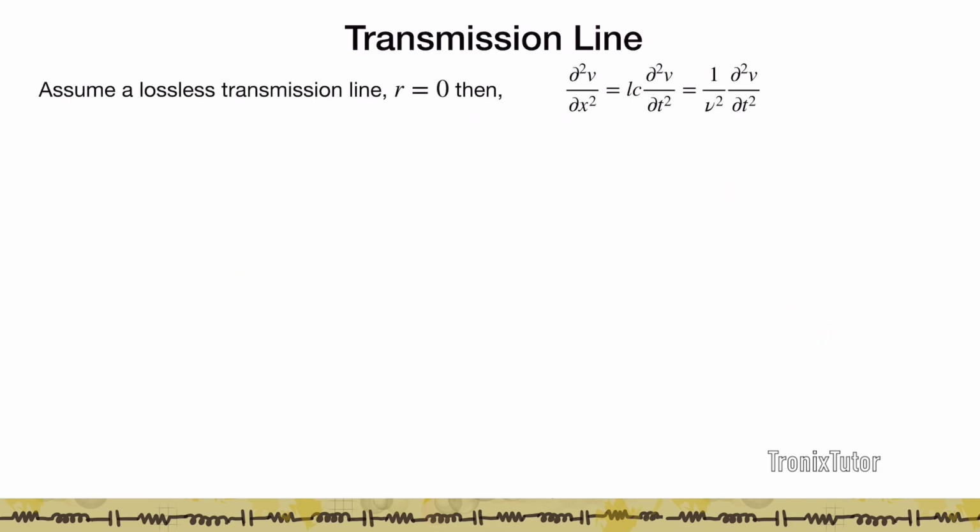So again, if I assume that this is a lossless transmission line, here I'm trying to deduce what the impact would be. If I assume that the resistance is negligible, because remember normally inductances kick in for the top layer metals where the resistance, unless you're working at very high frequencies, is not high, what you end up getting is an equation of the transmission line here.